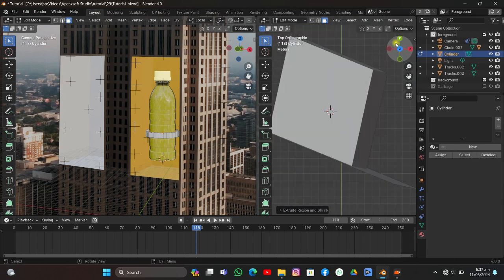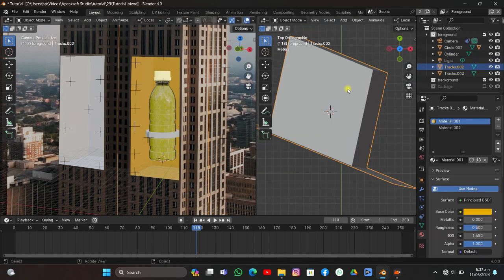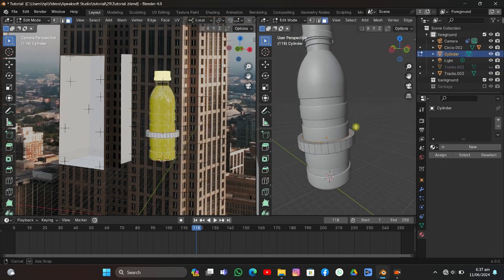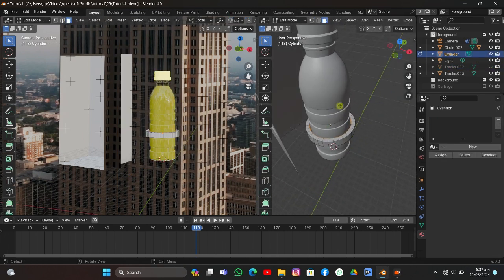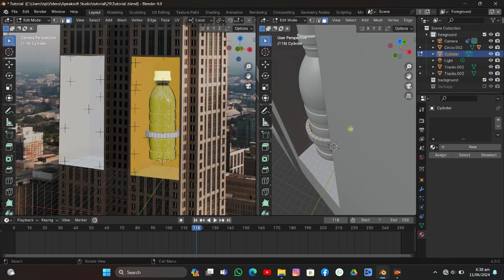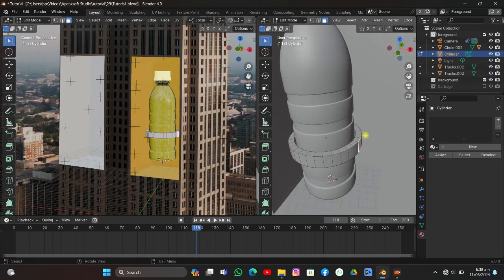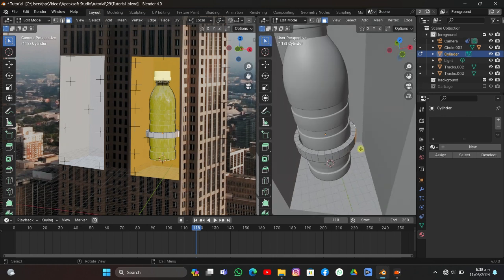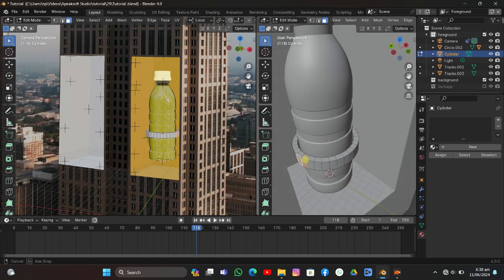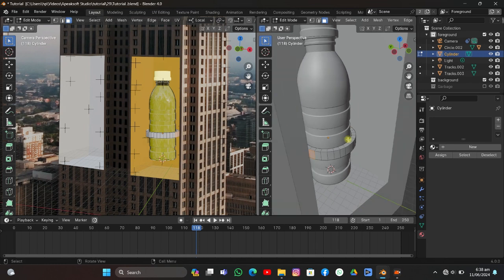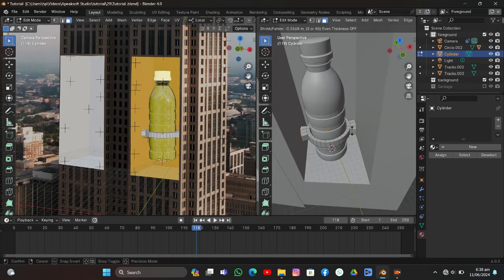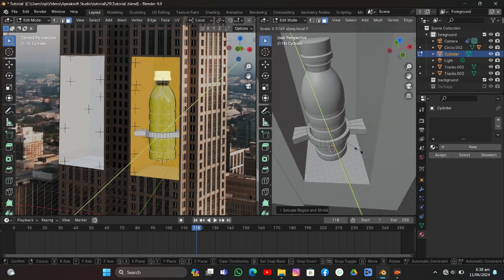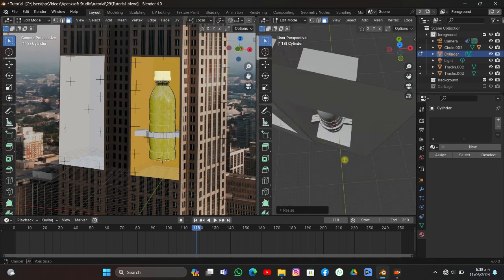And we're going to go to the top view like that. I'm just gonna select the cylinder right up here. I'm gonna select some of the edges here, because I want to extrude it on this side, also on the other side. I'm selecting 3 faces here, so we have something that makes sense for us, that is attached to the wall like that. Okay, so by hitting Alt E, I extrude it by normals,